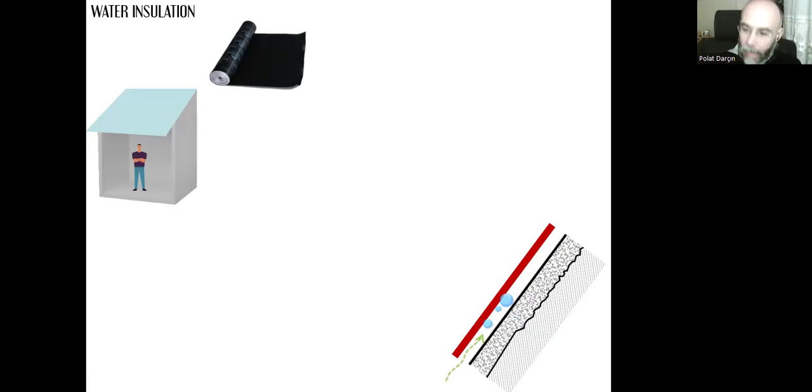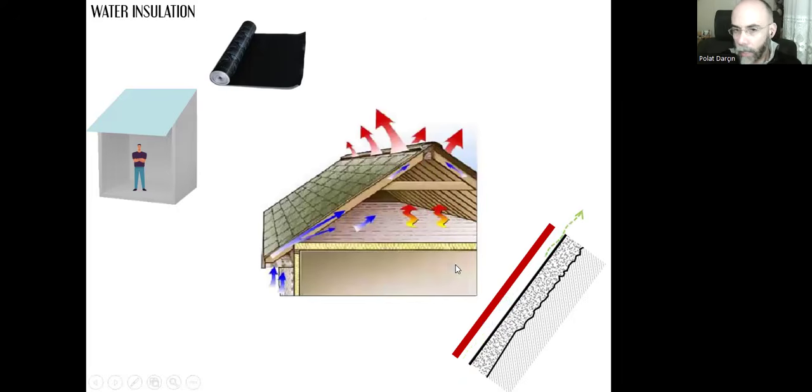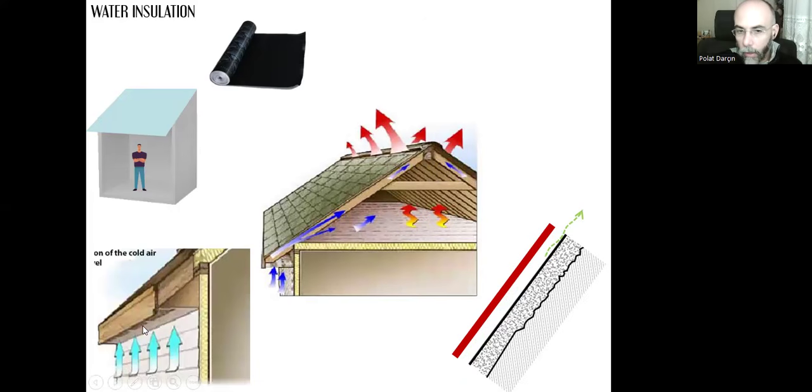And if we let a natural air circulation through this channel, we can sweep up the excessive gas. How can we do that? We can have this air intake at the eave level. We can create tiny gaps here at the eave level and let the natural air pass inside this channel.